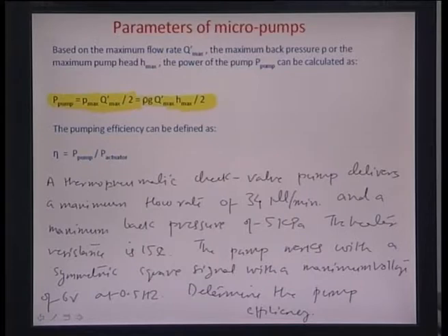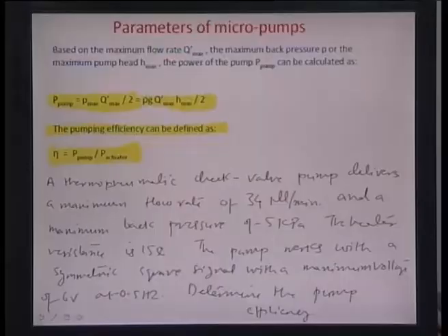So, based on this power equation, we can define pumping efficiency as the power that the pump actually generates in terms of flow by the power that it takes in terms of actuation. So, if you have certain energy delivered per unit time inside the pump, which causes the mechanical or the non-mechanical actuation of the fluid, and then it results in certain work done by the fluid flow against the pressure head, etc. So, the ratio between these two would determine the pumping efficiency, as to how much of the energy which you are packing in is converted into energy applied for flow inside the pump.